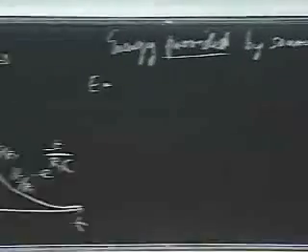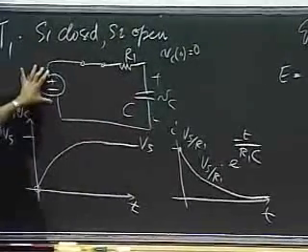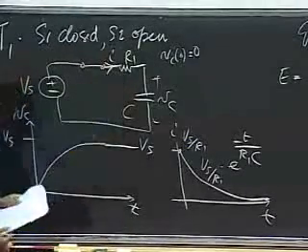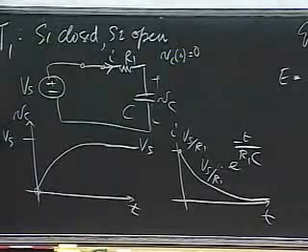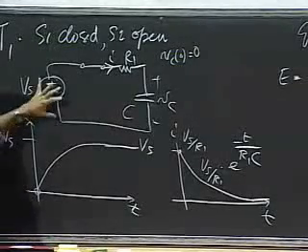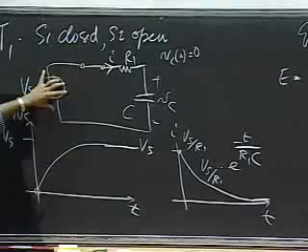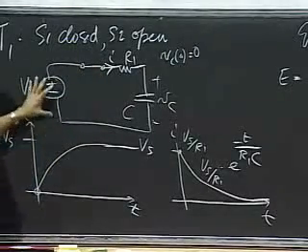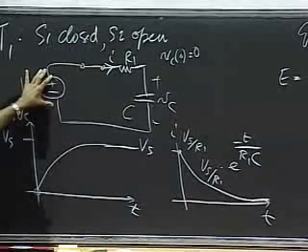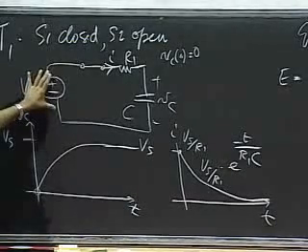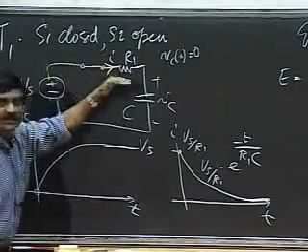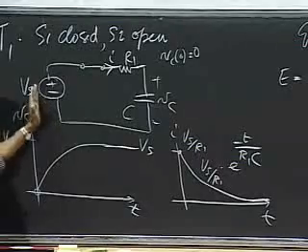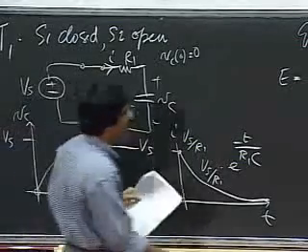So the energy supplied by the source is simply the voltage across the source multiplied by the current being supplied by the source. This is I. Remember, by the associated variables convention, if I have a voltage across some element and the current into the element is positive, then that element dissipates power. If the voltage here is, say, 1 volt and it's supplying current, if the I is out in the other direction, then it is supplying power. So in this case, the current I is going to be heading outside.